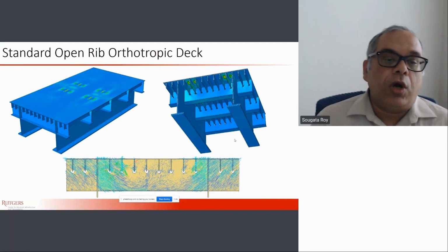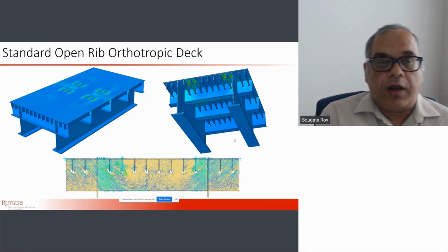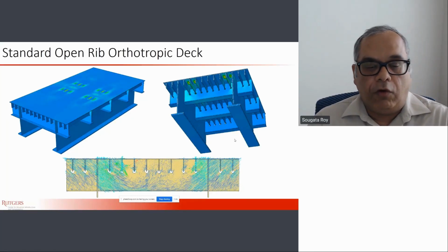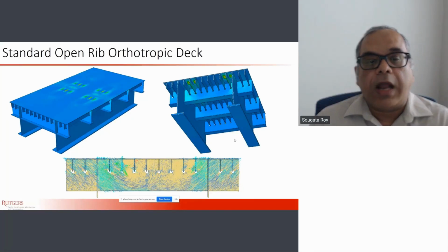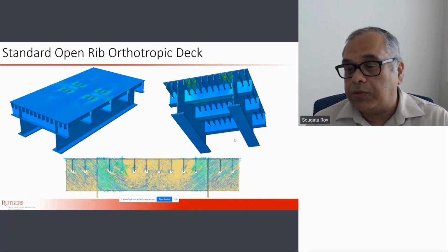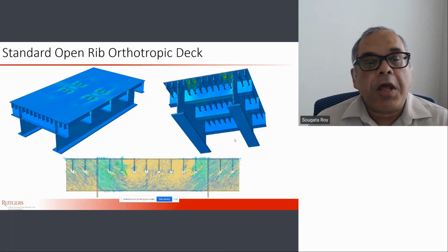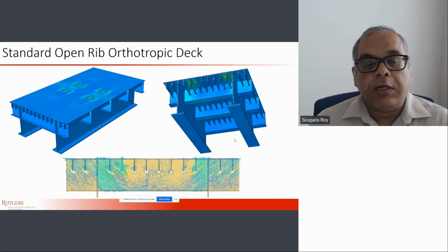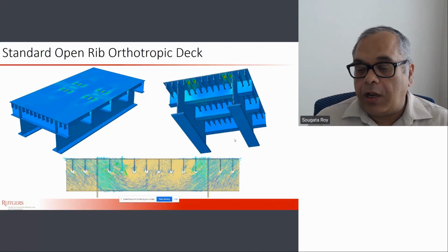If you have 2 girders, it's a stable configuration, so you can have another 2, and then you can have a joint in the deck slab and between the floor beams and so on. Then you can have a modular construction of bridge decks for short and medium span structures very quickly. This is also very efficient. It has less fabrication demand than the closed rib fabrication has, and as a result, this is a very viable option. So this is a project we are currently working on.